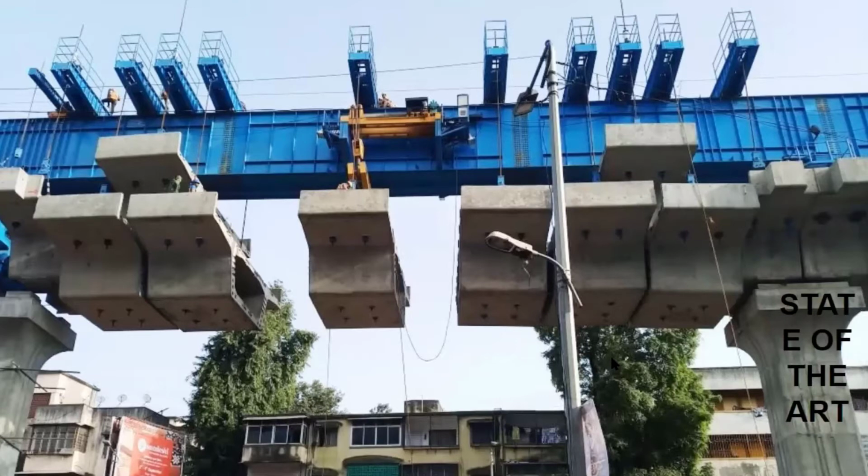So during the construction, we have very small elements. Typically, the element length is about 3 meters maximum, and they are being joined together. So at this point of time, also many loads will be acting on these elements, and they need to be structurally stable. They need to remain intact before they are put in place. So in our structural modeling that we do in the software, I'll discuss which software to use for that modeling.